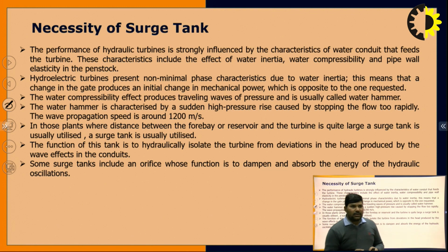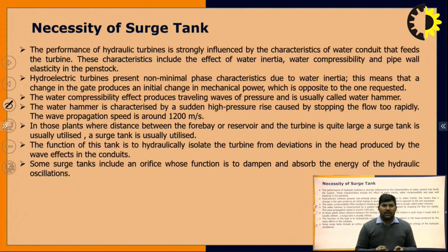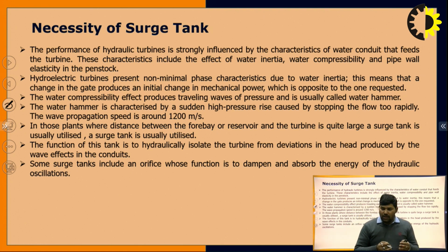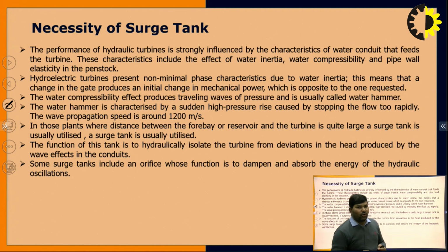The water hammer is characterized by a sudden high pressure surge caused by stopping the flow too rapidly, and the wave propagation speed is around 1200 meters per second.